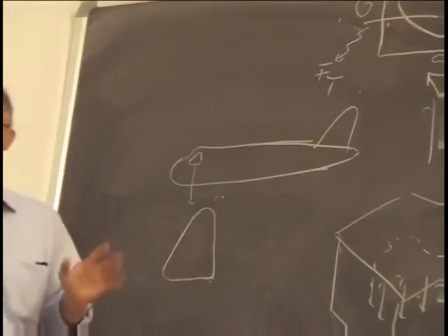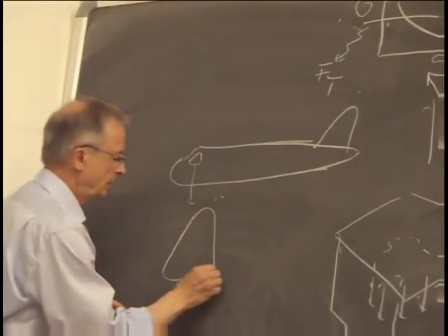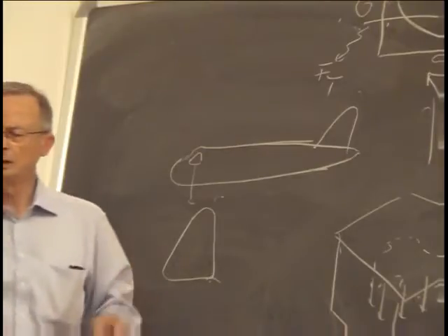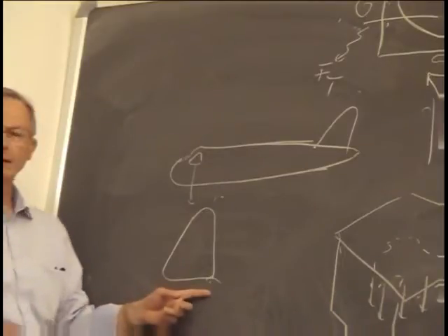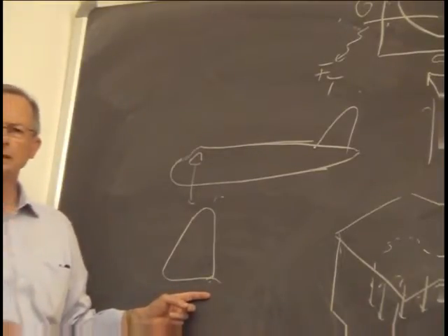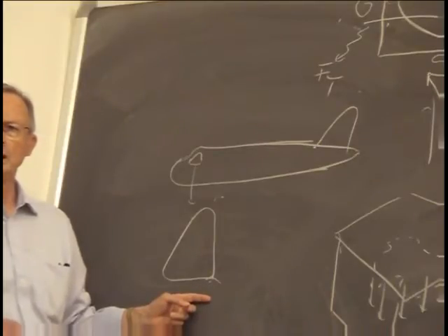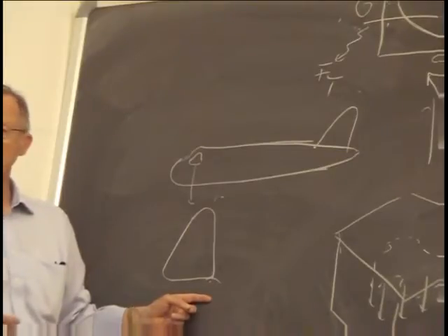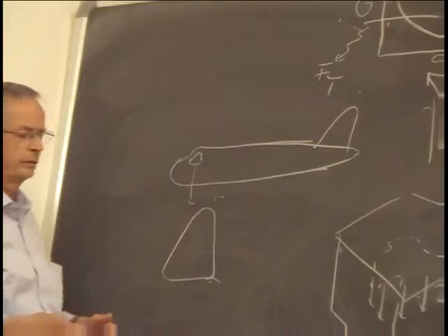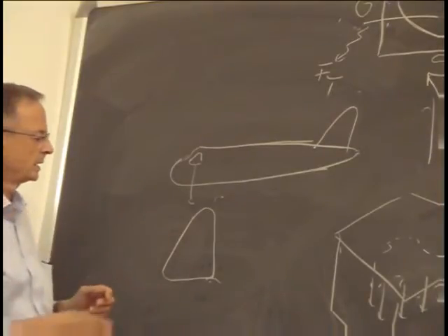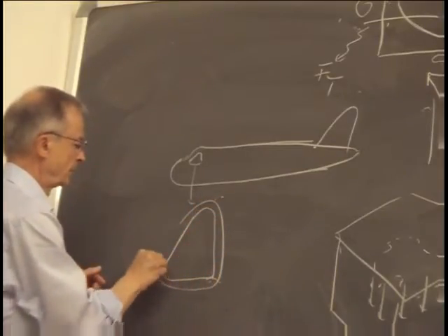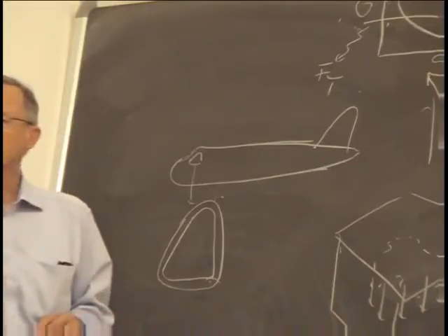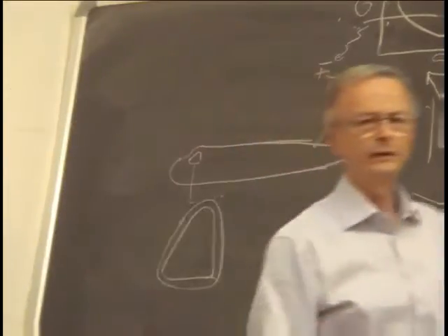And in one of the corners, I don't know which one, a crack initiated during loading, and the crack became critical before there was a chance to detect it, and 2 planes were lost. They broke, the fuselages broke at cruising altitude, and the reason was, what people told me, I hope that it's correct, that they did not remove the plastic liners here around the window. And the crack became critical before it had left this liner.